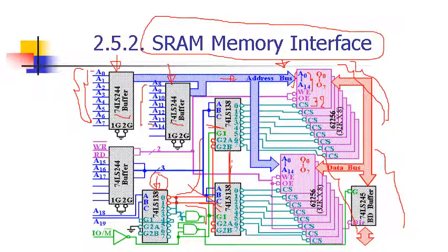All right, we're given some address range. Looking backward to the address range given, you would see that, okay, A15, A16 and A17 are now used to select one of the memory locations, either upward or downward. They are never activated at the same time.